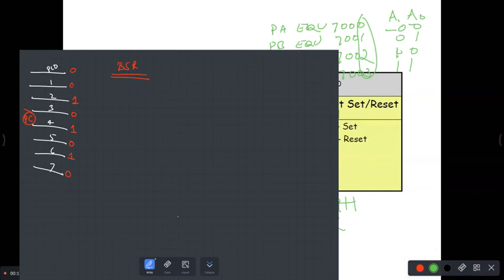It's very easy to remember the bit set reset mode. Okay, tell me, what is the control word for this? I'm going to write only for this: 0, 0, 0, 0, 0, 0, 0, 0. It is all 0. So to make this 0 using bit set reset mode, you move to the AL register 00H, then just the OUT instruction, OUT control register, comma, this is the port address, assuming that it is already declared using EQU. You know what is EQU, right? So OUT CR, comma, AL. Now, can you tell me what will be this?